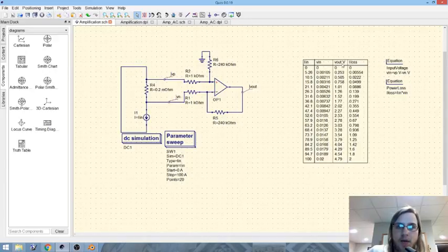So I can see my input voltage to the amplification circuit. And I can also see my output, which ranges from 0 to a little less than 5 volts, but this should be acceptable. And also what I want to see is the loss due to current, and so I just calculated that by multiplying my In times my Vn. And so what that tells me is how much wattage is going to be lost due to the measurement. So when I'm at 100 amps, there will be 2 watts that will be lost across this resistor, which I've been told is not going to be too big of an issue for this application.